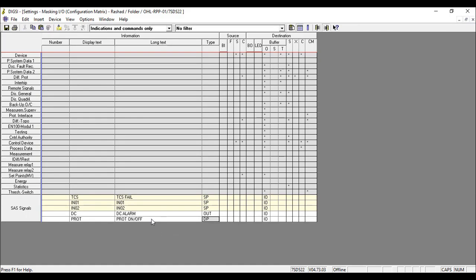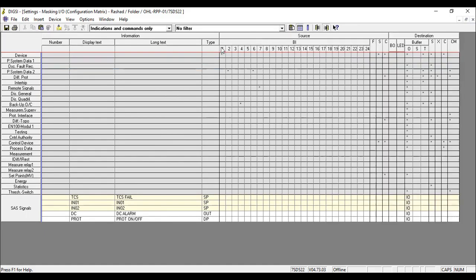First signal, Trip Circuit Supervision CID. Source comes externally via binary input. Assign it with Trip Circuit Supervision regardless of relay pre-programming, delete and assign binary input per drawing. External through a binary input, so I start by assigning the binary input with Trip Circuit Supervision or with this input. Of course, regardless of the relay's pre-programming, I can delete it all and start from here by assigning the binary input according to the drawing I have.